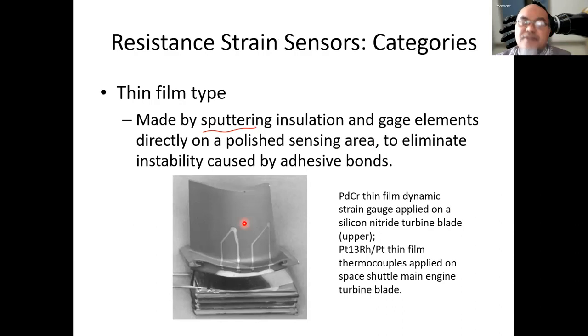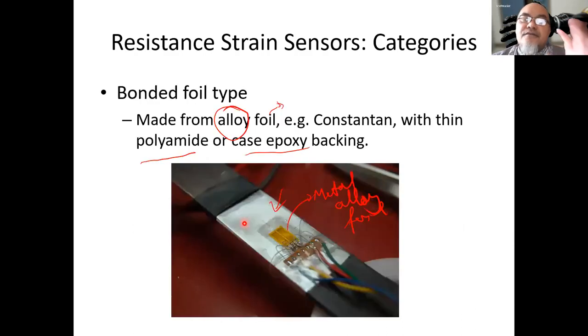There is an interface between the two materials, so the difference between the thermal expansion coefficients may not be that significant. However, if you have the strain gauge material coated on a polymer, and the polymer itself is attached to the steel structure using epoxy, using glue, the glue has a different thermal expansion coefficient than the steel whose strain you want to measure.